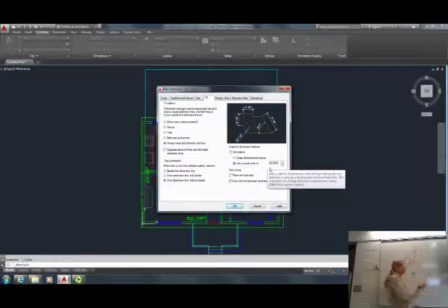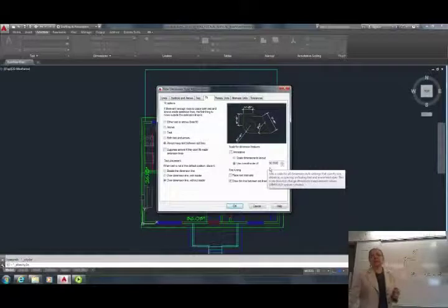1/8 of an inch equals 1 foot equals 12 inches. That's easy, right? Now if I don't want to have fractions, I've got to multiply both sides by 8. So it's basically saying the same thing as 1 equals, what's 8 times 12? 96. Now, if you're working in metric, you would know that you have to put scale 100.